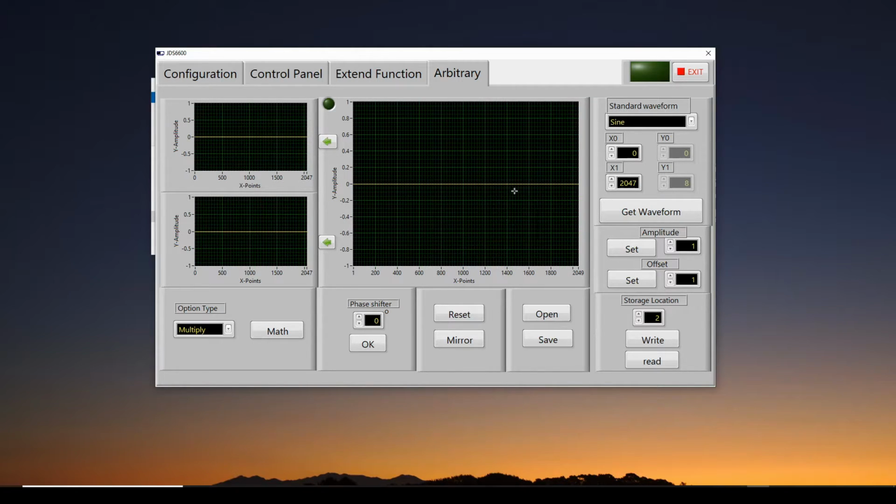So we're basically going to want to bring a sine wave into this center display and set it up to be the right relative frequency, and send it over here as waveform 1, and then bring another sine wave in at the other frequency and send it over here, and then hit multiply to multiply those out, and that will give us our AM waveform, okay? You've got to hit that math button and it will multiply it and generate, and we'll go through and do that.